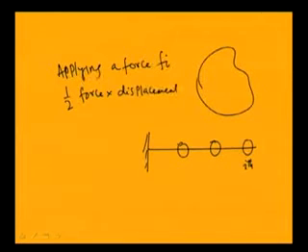When you are applying a force Fi here, and at other places you are not applying any force, the displacement at this position will be Fi into Aii, as due to a unit force at the ith station the displacement will be Aii.